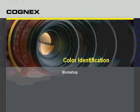Color monitoring can be used for color identification or classification, and just strictly color monitoring, making sure that our main average color doesn't deviate much from what we learned. And color identification tools are used in applications where we need to identify between parts that have a specific color content, where the ratio of the color content is the same. Again, there is no pattern learning in this case.